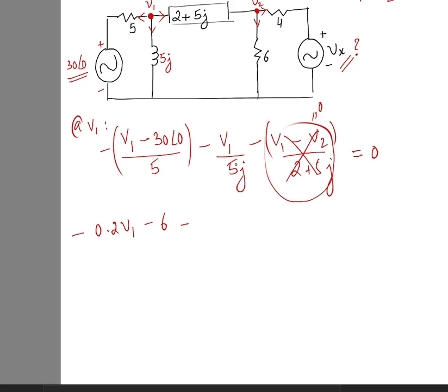In your calculator, press the shift button and the plus button at the same time, right? And then it will open something called Pol in your display. You'll first have to enter the real part, which is 0 in this case, and then the imaginary part, which is 5. When you enter this, it will convert the rectangular form into polar form, and in polar form this is basically 5 angle 90 degrees, yeah.